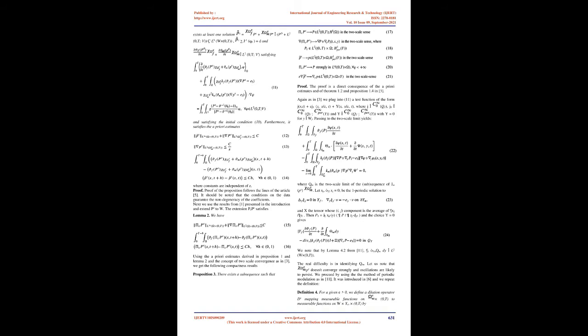We refer to [9] and [18] for the two-phase flows in periodic geometries and with the permeability of the same order, to the article [10] for the random case and to [11] for the two-phase dual porosity model. Very frequently, solutes are transported by an unsaturated flow. Single-phase unsaturated flows are described by the Richards equation. Even if it seems that the equations describing the two-phase flow of water and air are more realistic, the Richards equation is widely used and in the hydrochemical computer codes one should solve it in a heterogeneous medium.